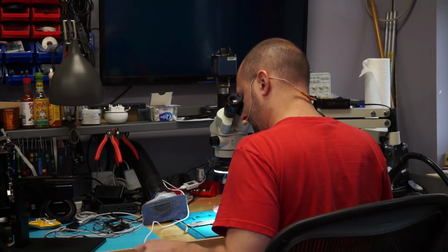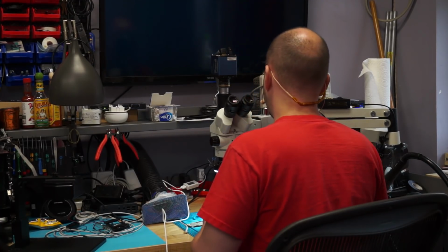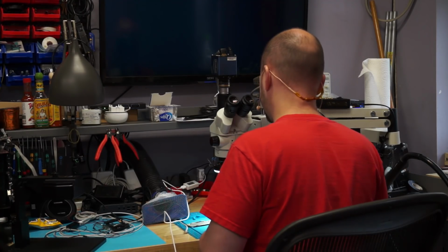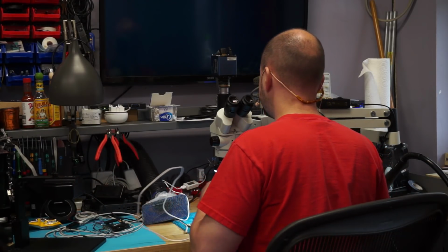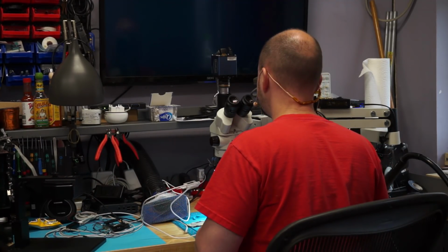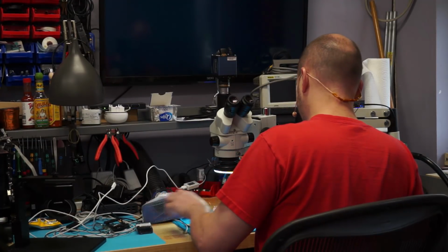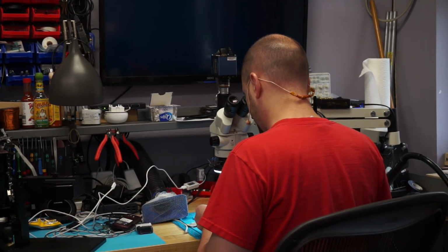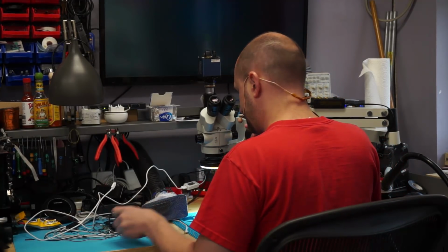Now if I plug this one in, I'm not getting any boot. And it's taking 1.75 amps. That's not good. I'm at 5 volts, 1.75 amps. So that is definitely different here, and it's doing something it should not. So we have to have a short on this board somewhere. So let's put it underneath our thermal cam and see if we can find a short.